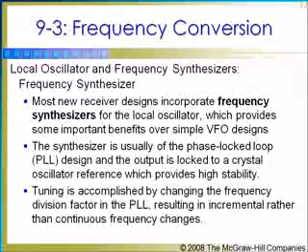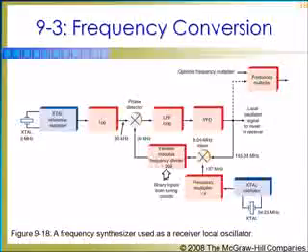Most modern receivers, from AM or FM car radios, stereos, and TV sets to military receivers and commercial transceivers, use frequency synthesis. As stated previously, one of the disadvantages of very high-frequency PLL synthesizers is that the VFO output frequency is often higher than the upper operating limit of the variable modulus frequency divider ICs commonly available.